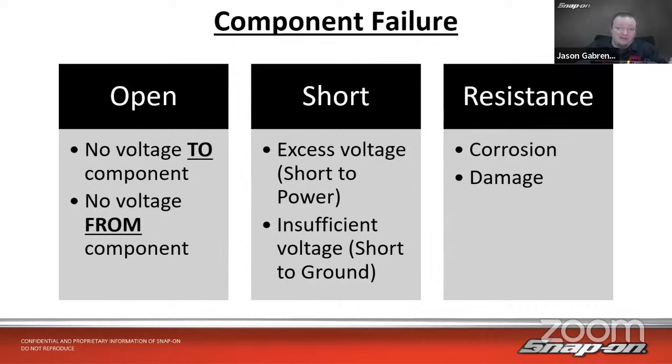So it's a 5-volt reference signal and it's shorted to a 12-volt line. Now it's getting excess power, too much, a short to power. Or insufficient voltage, where I have a short to ground.